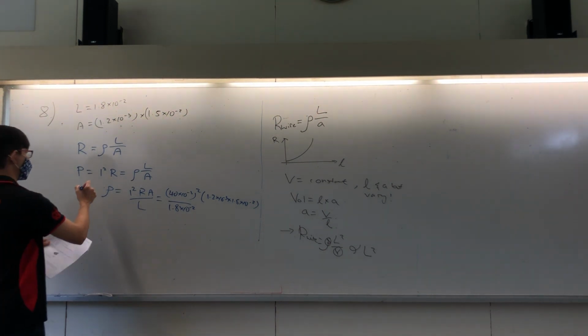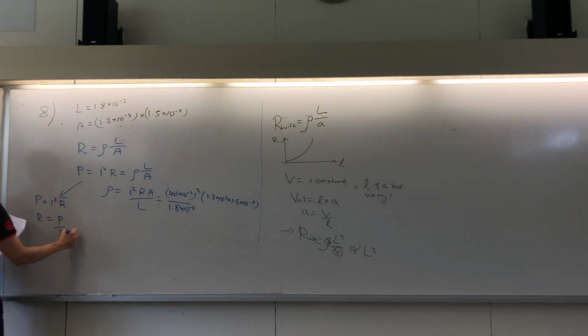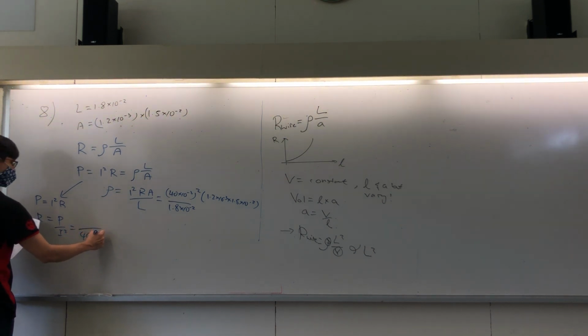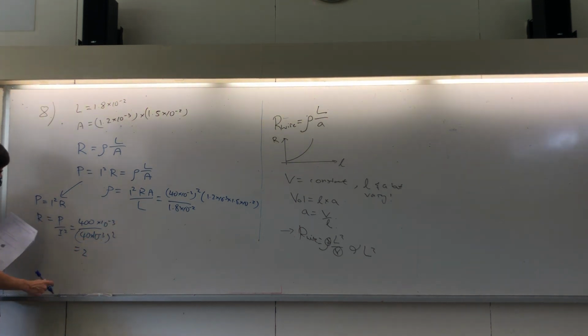Yeah, correct. So I'm going to need to use it to find the resistance. P equals I squared R, so the resistance is just P over I squared. Okay, so it's 40 milliamps and the power is 400 milliwatts. 250, huh? You know, it should be a nice number.